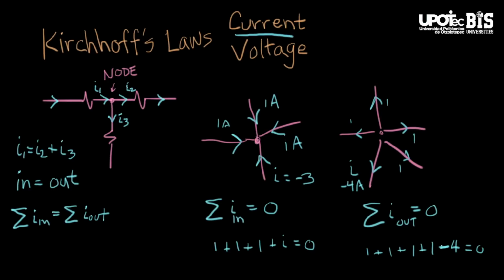So that's the idea of Kirchhoff's current law. It's basically we reason through it from first principles because everything that comes in has to leave by some route. And when we talked about it that way, we ended up with this expression for Kirchhoff's current law. And we can come up with a slightly smaller mathematical expression if we define all the currents to be pointing in.